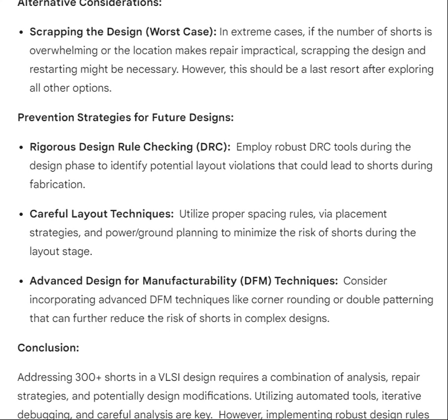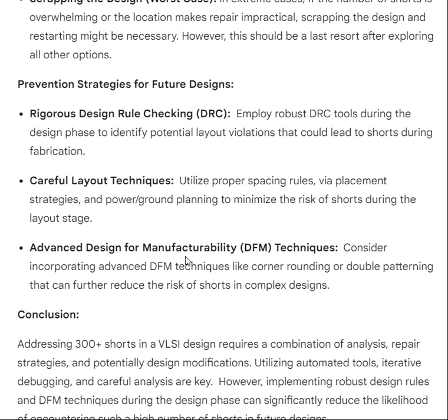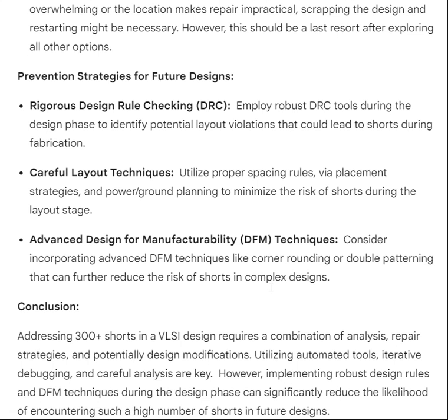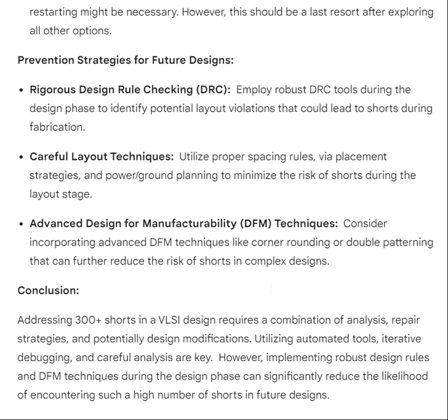Prevention strategies for future designs. Rigorous design rule checking, DRC. Employ robust DRC tools during the design phase to identify potential layout violations that could lead to shorts during fabrication. Careful layout techniques. Utilize proper spacing rules, wire placement strategies, and power, ground planning to minimize the risk of shorts during the layout stage.